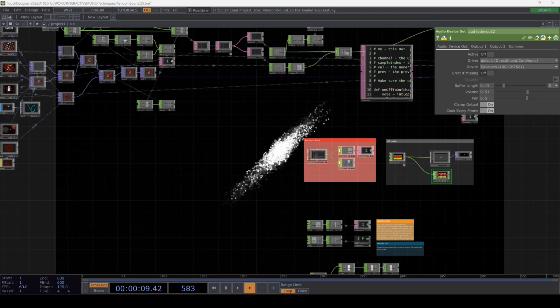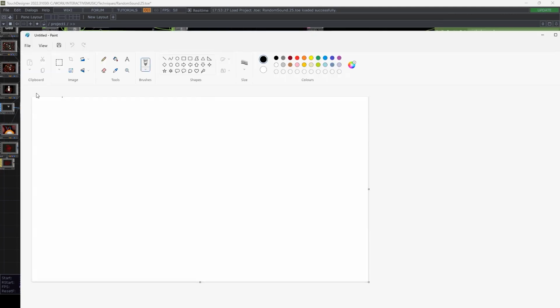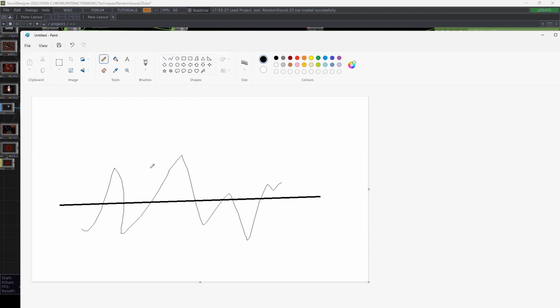That's not possible because, for example, imagine we have a sound card. It has 0 decibels, and then we have some wave which typically goes until 1 and -1, which is a normal undistorted sound range. And in the case that we work with control voltage, we can easily have a static signal of something around +5 volts, which would in several milliseconds destroy any sound system.